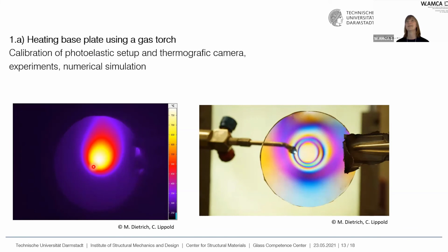But you have to manage the temperature, and this is also something you have to monitor. Per se all cracks might be healed in the flame, but the moment I turn off the flame, my specimen cools down, I still have my temperature gradient and get into a regime where cracks might grow.